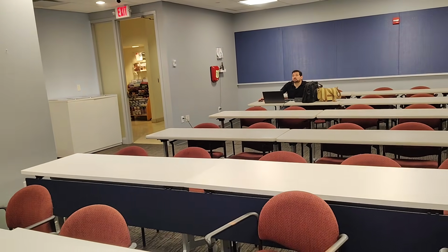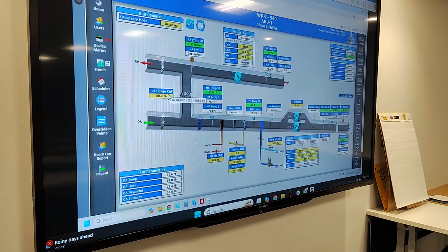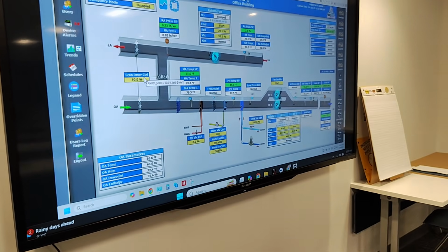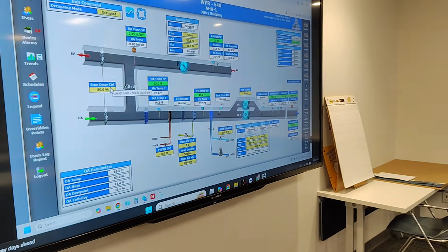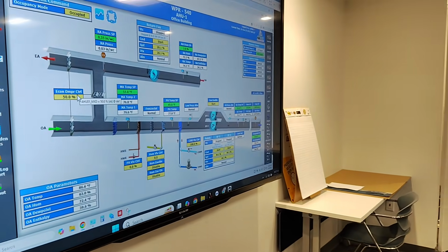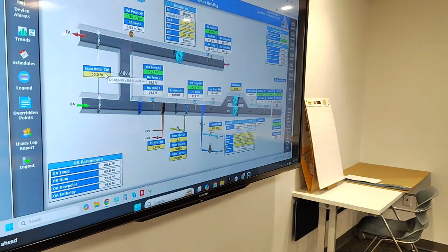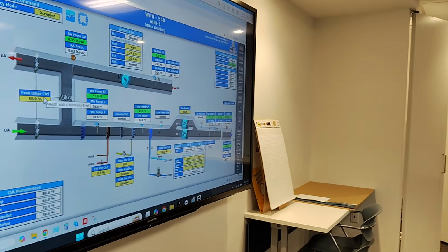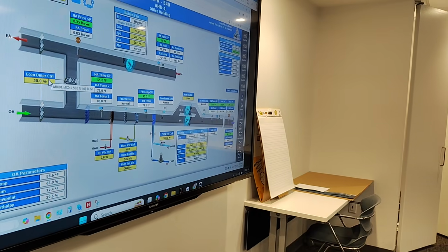But you can't directly control those dampers. You can override them, but the control of those dampers is based on programming. Okay, but last week we had an issue where the conditioned air was being dumped out on the roof, and I had Dan next door close them so that nothing would get spilled and it would go back into the system, because it was dumping and then bringing in hot air. Yeah, I get it.